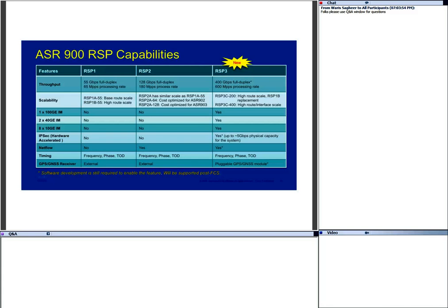So remember, I talked about how the ASIC is capable of doing 300 million packets per second, but we still haven't enabled the full capability. So that's where the number 600 comes from. At 400 gigabits per second, we have 2 ASICs and 300 million packets per second, just multiplied by 2 for 2 ASICs, and then you get that 600 million packets per second.